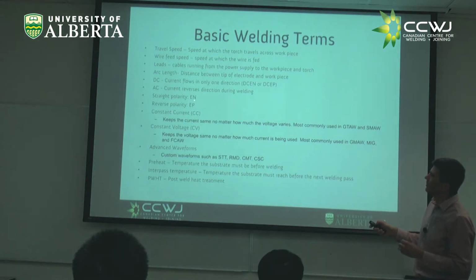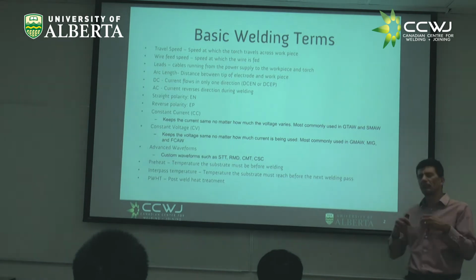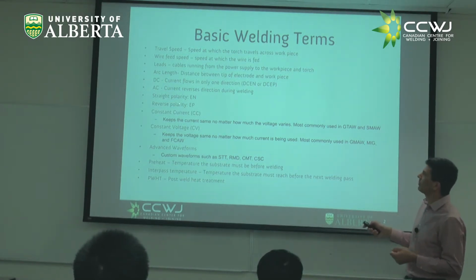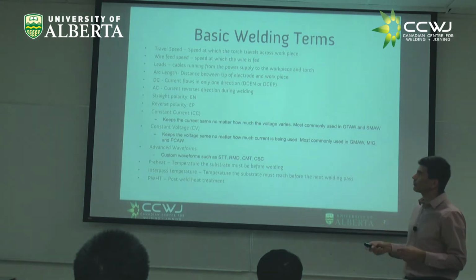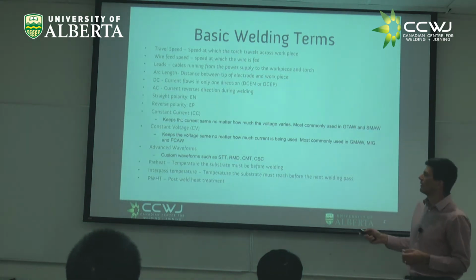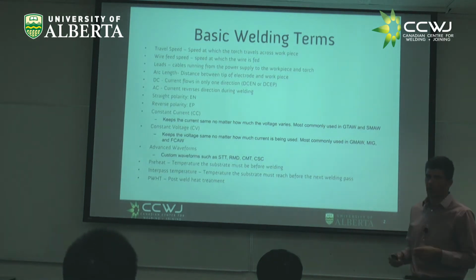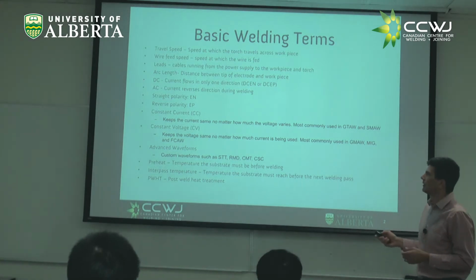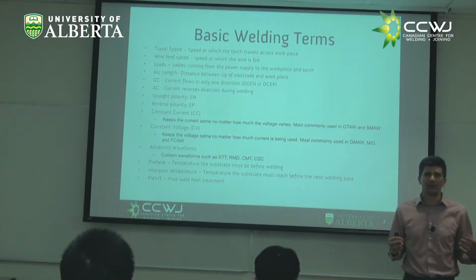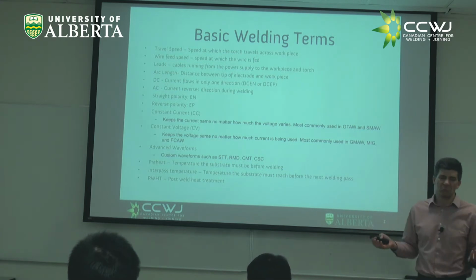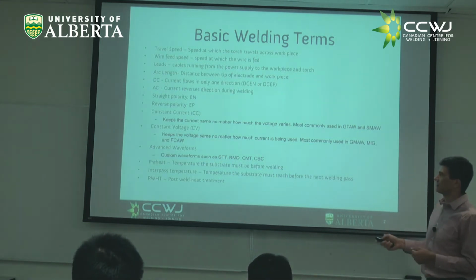This I put here so you know, but for some reason that is historical, in welding people typically call electrode negative straight polarity. And when the electrode is positive, they call it reverse polarity. That's for historical reasons. Because some processes run always in electrode positive, and nobody would say that the process is reversed.